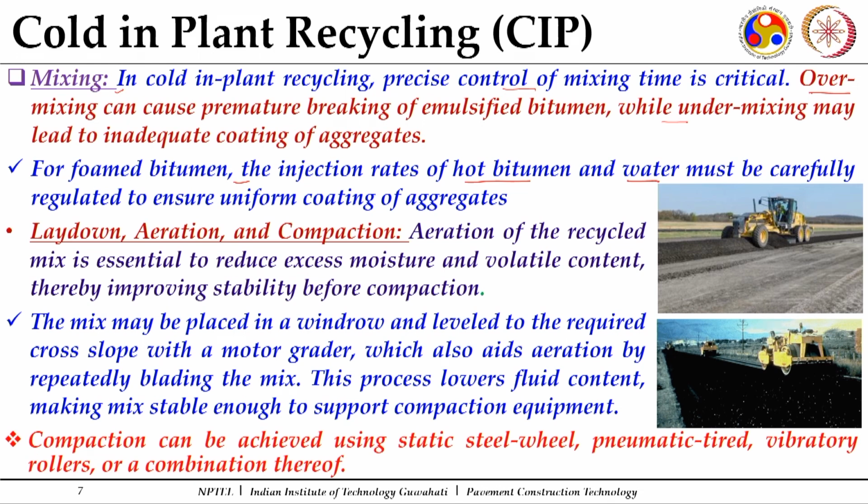So, another aspect we need to know is the half life, which is the time by which the expanded volume of the foamed bitumen gets reduced to half of its initial volume. These are some important characteristics which need to be understood when we are using foamed bitumen in cold in plant recycling also.